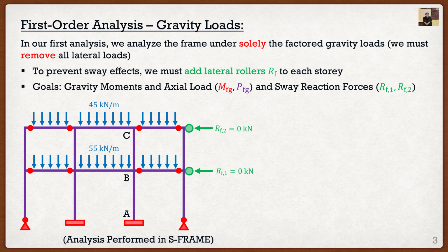And you guys are going to say, Clayton, why is that? Isn't that convenient that it's equal to 0? And yes, it is. So here's the first trick that you can have, and this is a very good trick for an exam type scenario. If your frame is symmetric in terms of geometry, stiffness, as well as loading, these reaction forces are going to be 0.